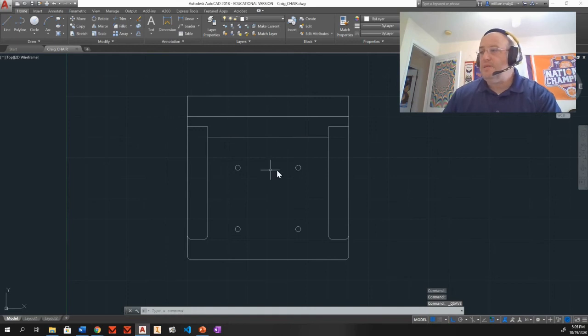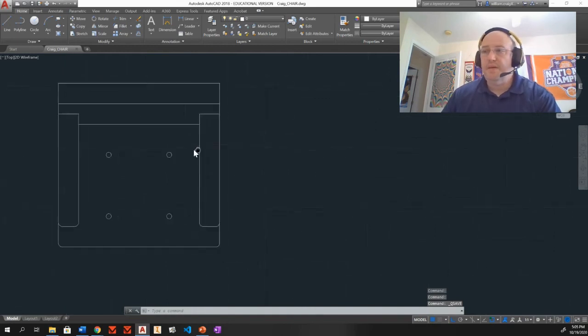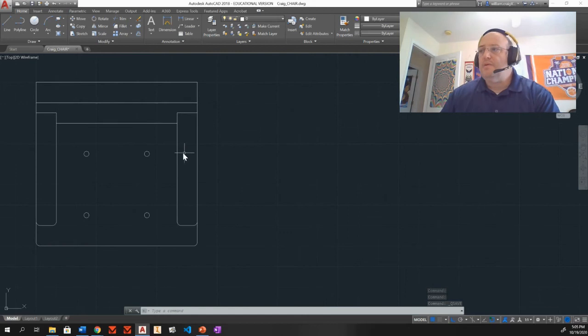And now I'm going to copy the chair. I'm just going to pan this over a little bit. In my settings originally, I set my minor lines to 4 inches. And since my minor lines are 4 inches, I went with a major line every 3. So I know that if I look at a block here, I have a 1 foot or 12-inch change.